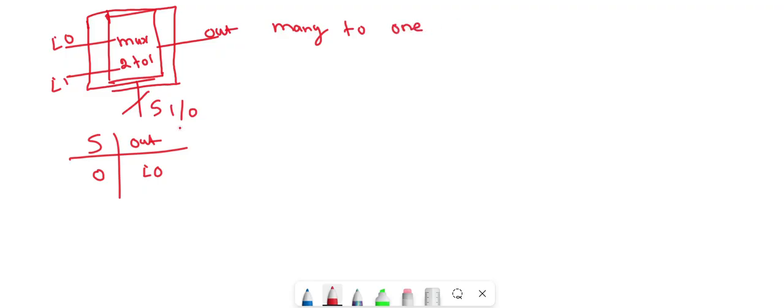Many to one concept. The two channels are multiplexed together and transmitted via a single channel. I0 and I1 can be either 0 or 1, whatever you want to transmit. I1 you can transmit 1, 0, 1, 0. So any data can be transmitted via I0 and I1.